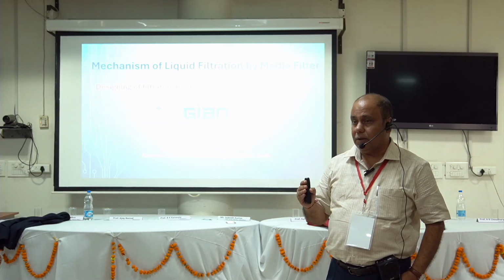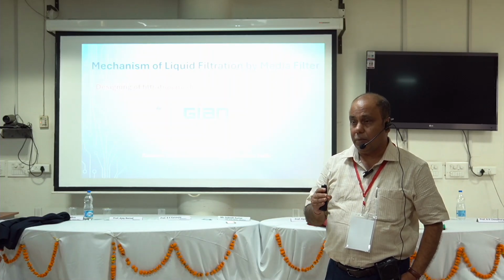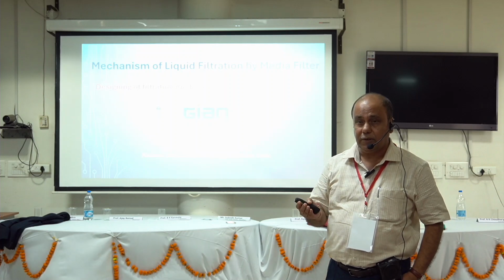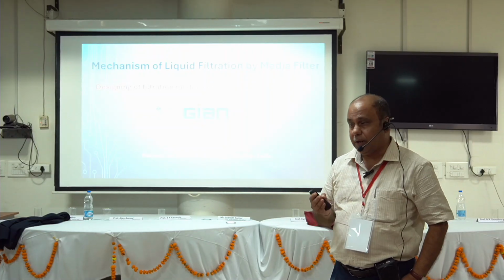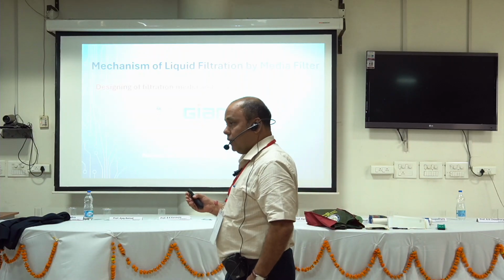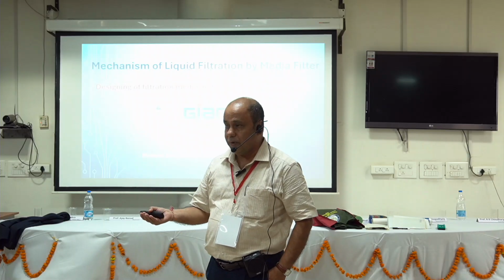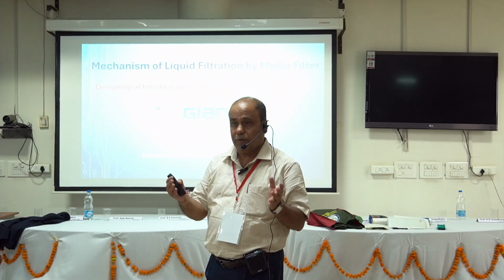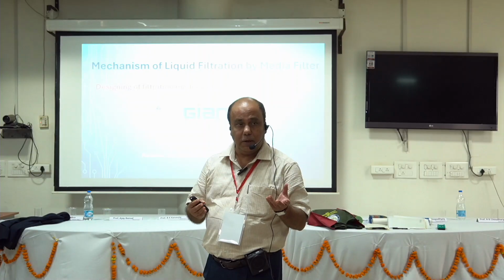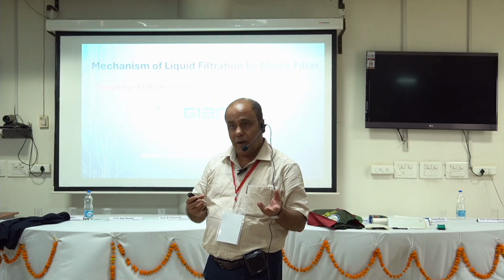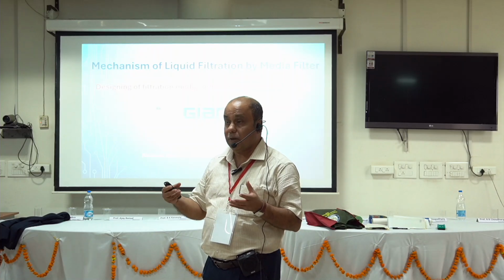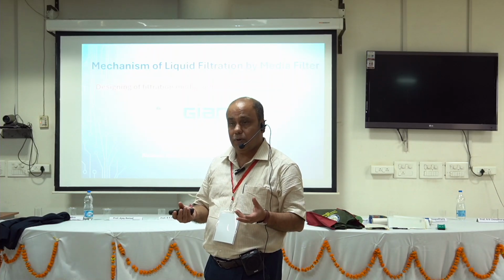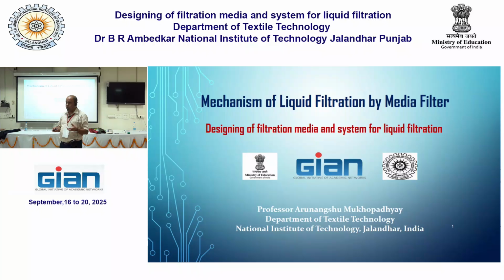One of the primary reasons is that whenever we talk about air filtration or liquid filtration, liquid viscosity is more and density is more. So whatever is applicable for air filtration may not be similarly applicable to liquid filtration. Suppose you give more focus to single fiber theory in air filtration; single fiber theory can have little relevance in liquid filtration, because the density of liquid is very high as compared to air, and the viscosity is also high.